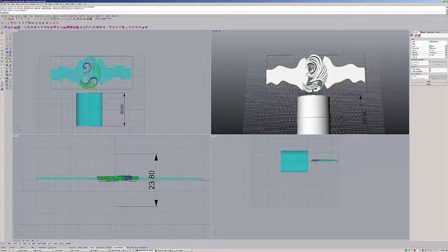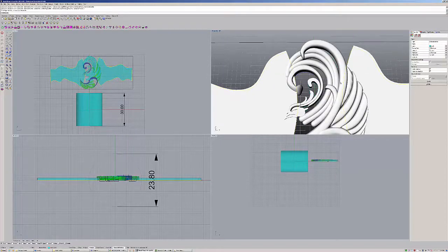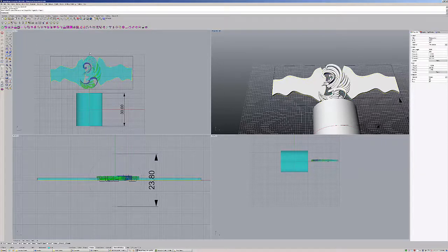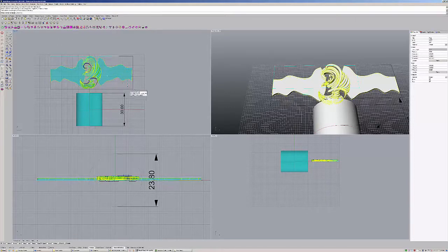Yeah, this is one way I can do it. I mean, I should really connect this over here, but I just want to show you quickly how I can make a shank. So again, now I'm just going to go under transform and flow along the surface. We're going to now choose all the objects, right click, first corner. After you click on plane, first corner, second corner, and then choose the target.